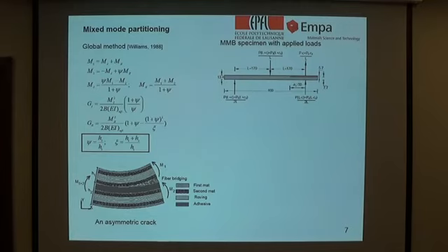So if I just want to summarize the equation, it is like this: when you have the same bending in the crack tip, I mean if you apply M1 and M2 in a way that these two arms have the same bending, then you have pure mode 2. And if they are inverse and the same bending, you have pure mode 1, because it opens the crack.